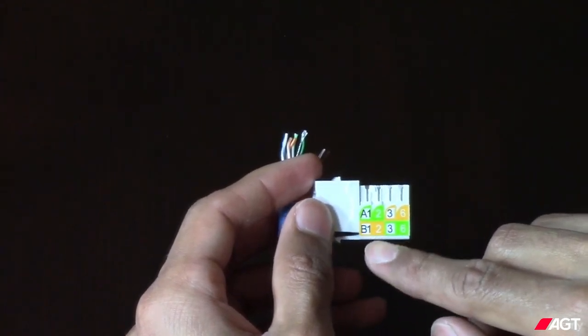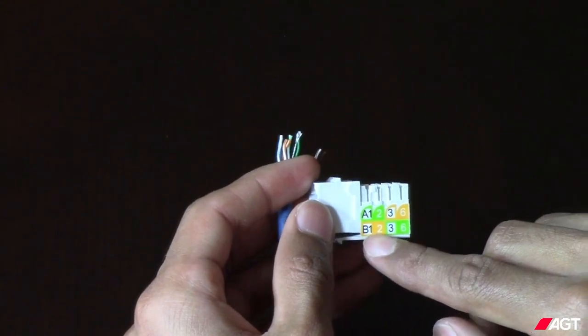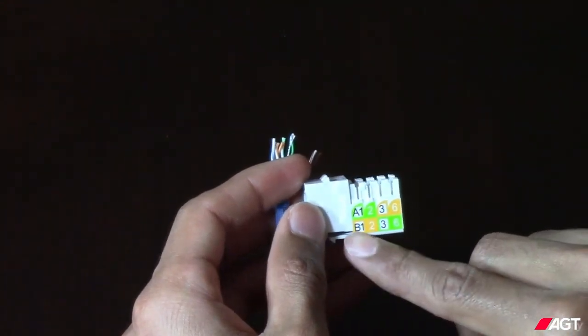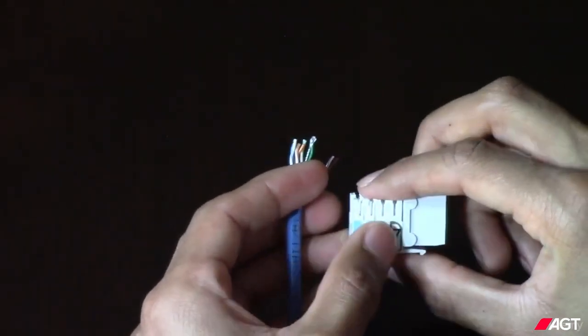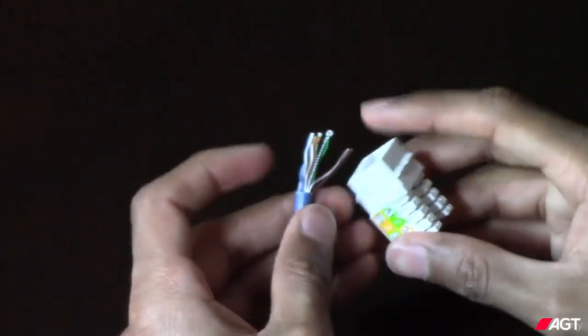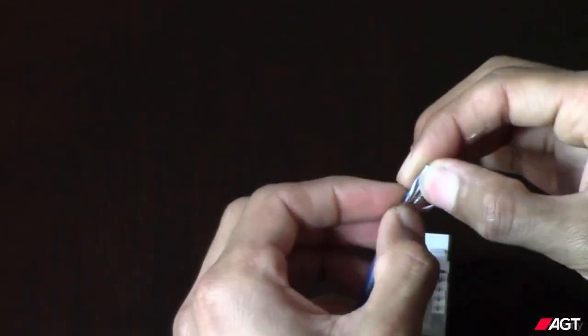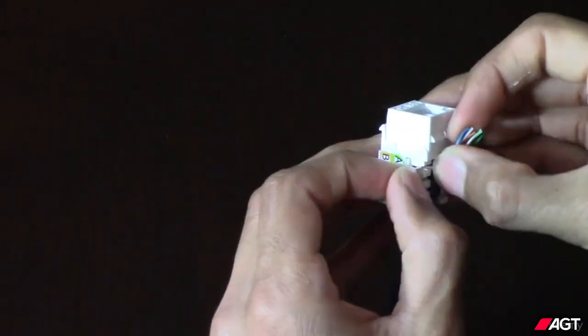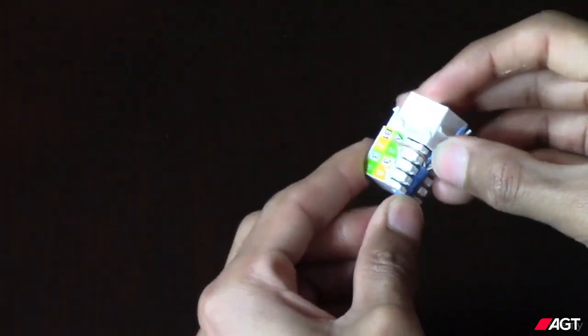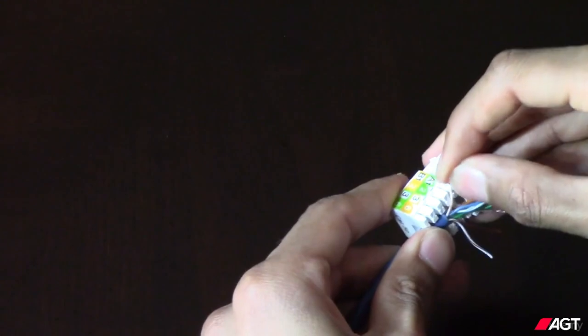Like I mentioned, when you're doing a wiring job, you want to make sure that every single cable that you create is the same pattern. And as you already know, the installation method is the same regardless of pattern. The only difference is the actual color pattern. So like with the connector, you don't want any exposed wire between the jack and the end of the cable. So make sure the cable's within the jack like this.